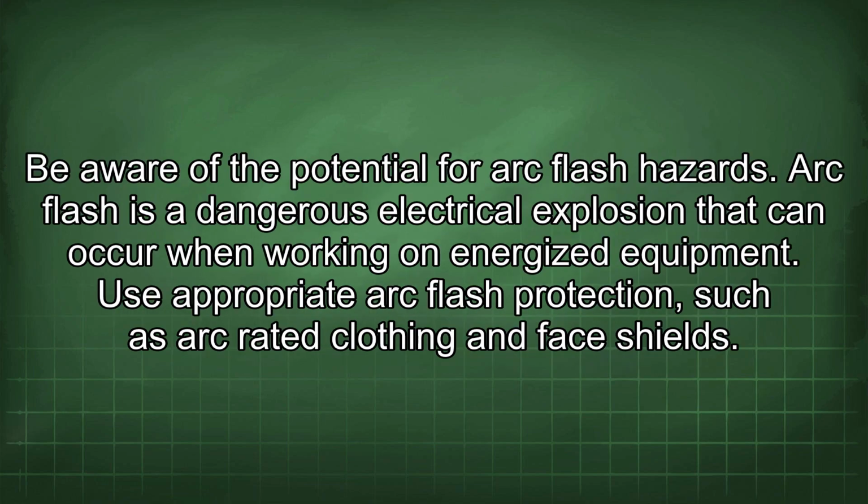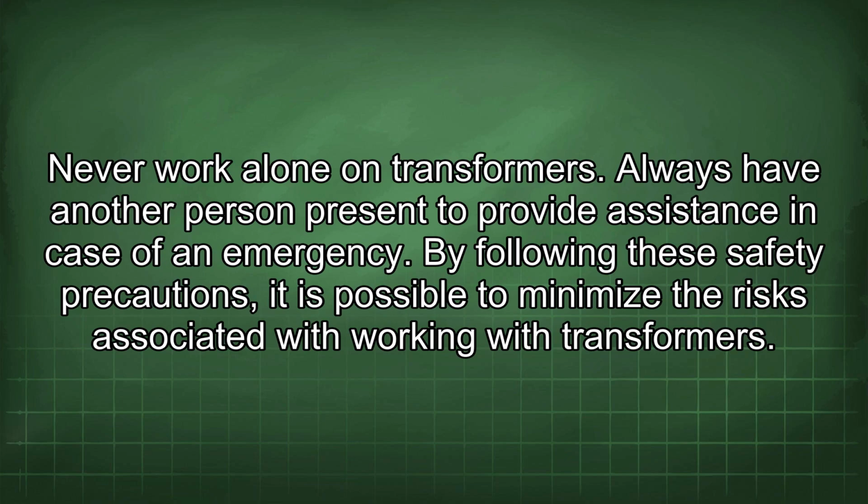Be aware of the potential for arc flash hazards. Arc flash is a dangerous electrical explosion that can occur when working on energized equipment. Use appropriate arc flash protection, such as arc-rated clothing and face shields. Never work alone on transformers. Always have another person present to provide assistance in case of an emergency. By following these safety precautions, it is possible to minimize the risks associated with working with transformers.